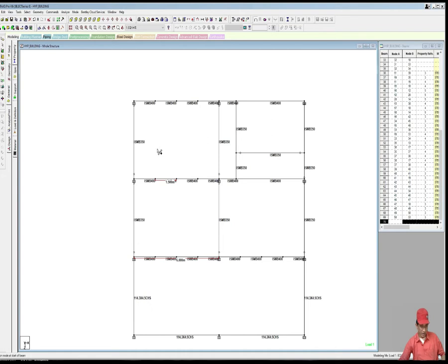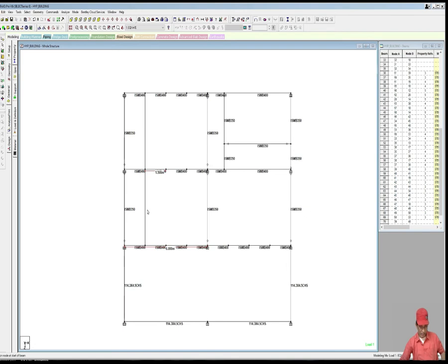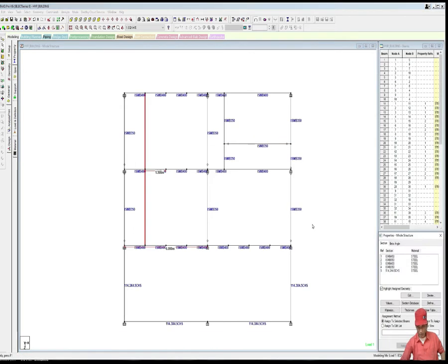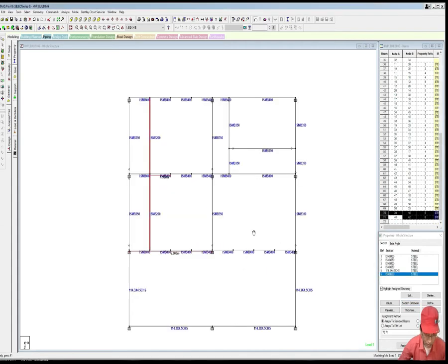Now go to the beam cursor. Take this beam. Make this beam. Now let us go to the property, because this will assign them a property, because it will help in copy pasting, because otherwise STAAD would say that the member has not been assigned any property. So we go to the property dialog box. We select section from the section database, Indian sections, ISMB 200, assign. Now the joists are actually simply supported beams, so we have to assign releases to this joist as well.